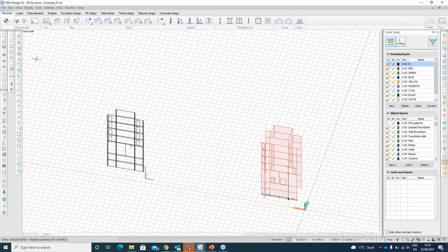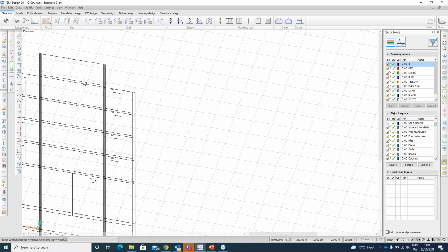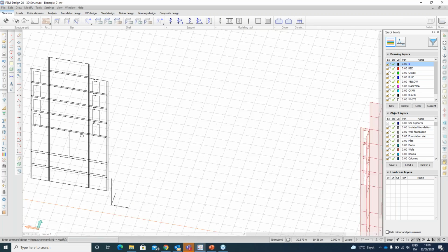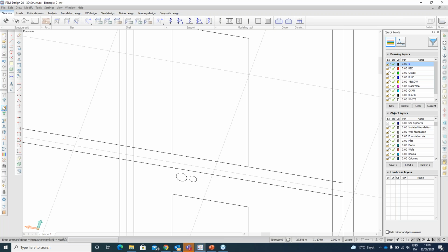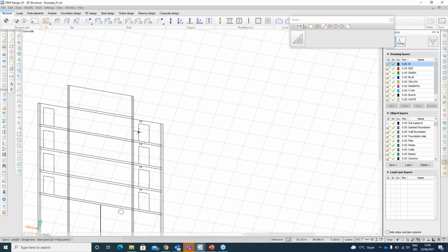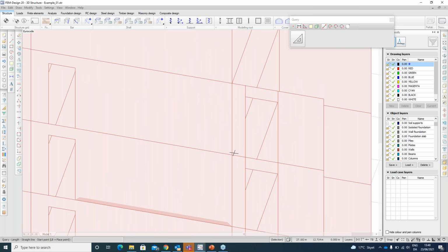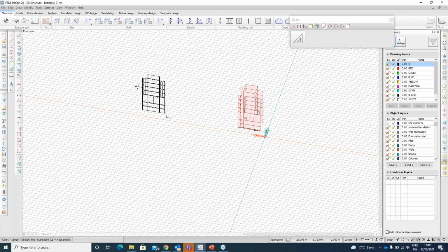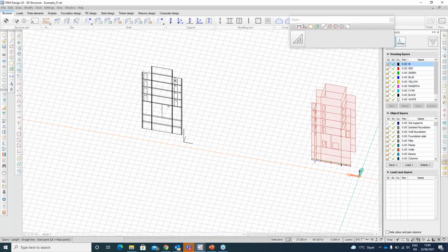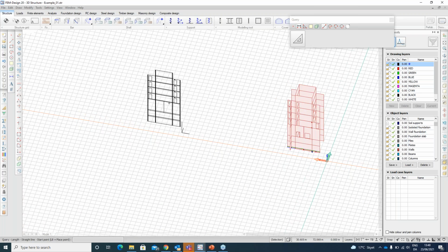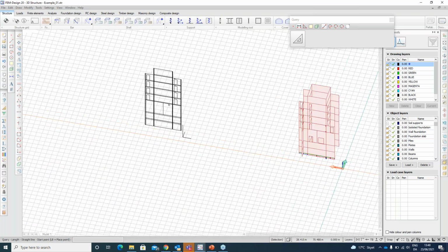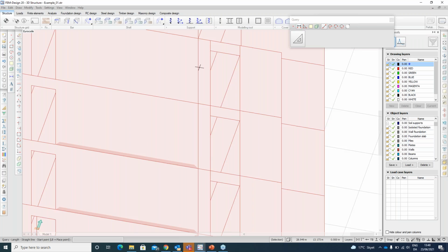It might be easier for you to, for example, okay, this door opening here, I can measure it. I can measure the distance from this opening to this wall at 650, and because the architect said that it will be moved, right here is 450. So I don't even need to have the drawing in my model. I can just look at it in my PDF or in my DWG viewer, and then do measurements on my model.